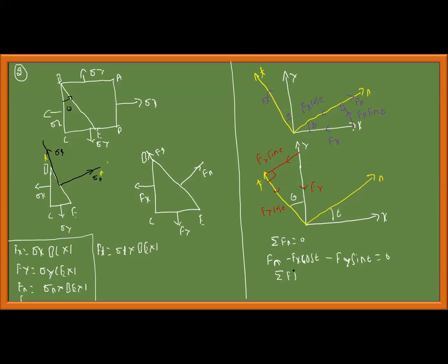Summation of tangential force should be equal to 0. Let me write f of t as positive, acting upwards like this. f of t plus here f of x sin theta, and here minus f of y cos theta is equal to 0. If you write this, your 50% job is over. Then it is just substitution and solving the equation. Okay, now I will solve this. Give me a moment.